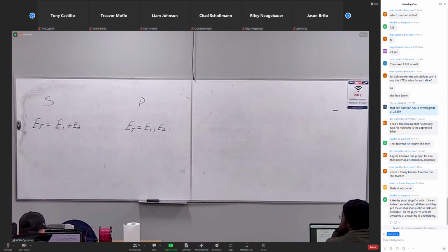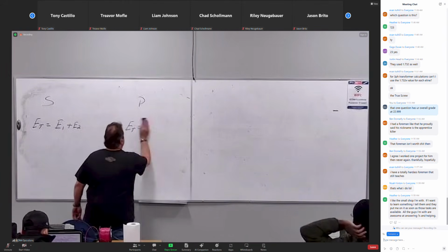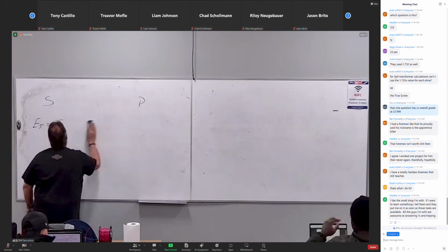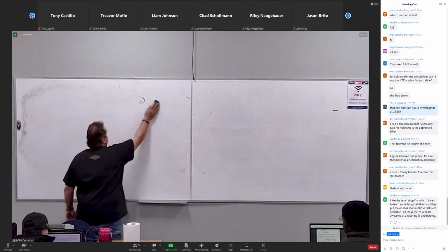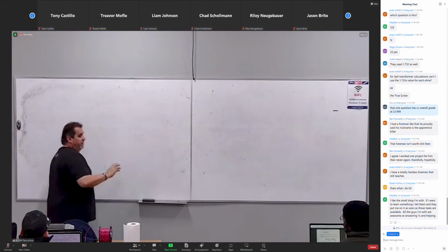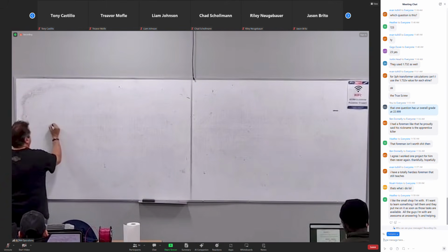Yes, no, maybe? Okay, cool. If I have a secondary that has 2 voltages, do you remember those rules? In series, each winding is additive. In parallel, each winding is what it is. So if I have a secondary windings.